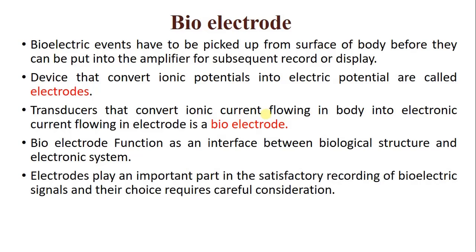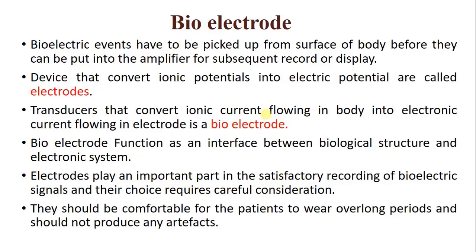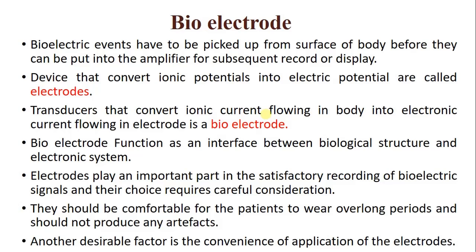Electrodes play an important part in the satisfactory recording of bioelectric signals, and their choice requires careful consideration. They should be comfortable for the patient to wear for a long period, and they should not produce any artifacts. That is, the bioelectrodes must not produce any kind of noise in the signal recording. Another desirable factor is the convenience of application of the electrode. That should also be considered while choosing the electrodes for any measurement of bioelectric signal.